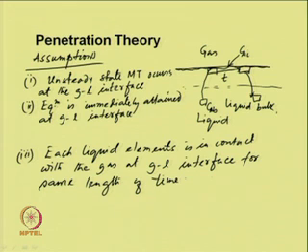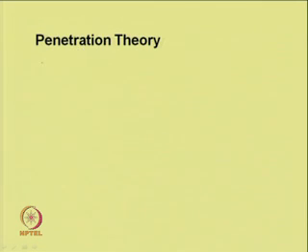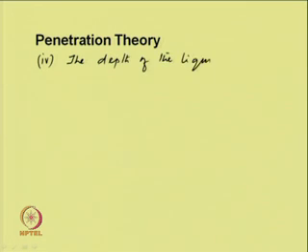This means that every element will travel from the bulk to the gas liquid interface and remain at the interface for t amount of time, each element having the same length of time, and then it is replaced by a fresh element of liquid. The fourth assumption is that the depth of the liquid is infinite.